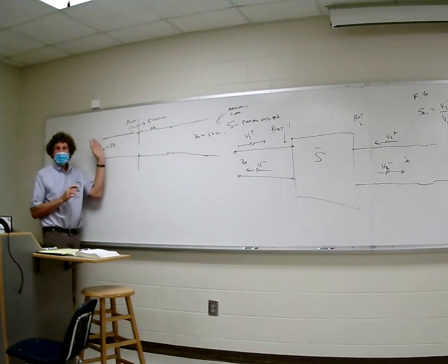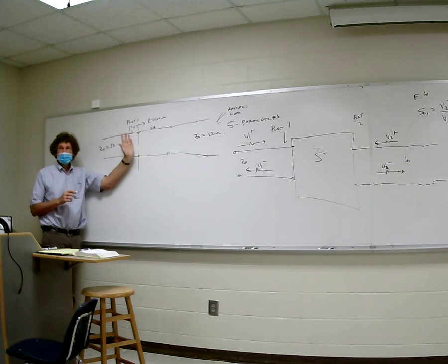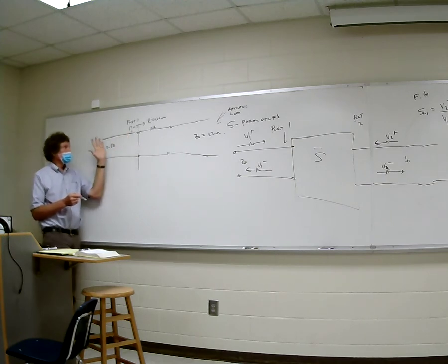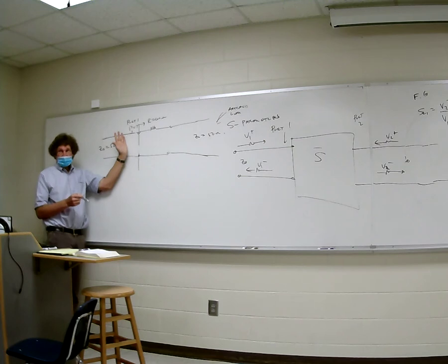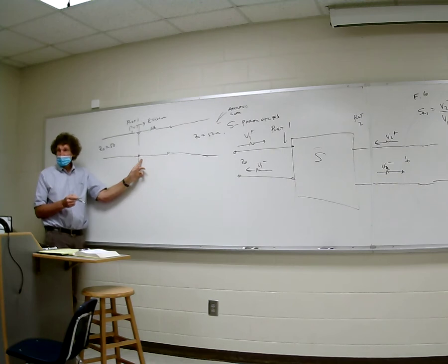Remember, this has got a characteristic impedance of Z0, right? So if I have V1 coming in here, at the instant it hits, it creates a waveform that's going to reflect. It would have the value of gamma times V1, right? And the superposition of that V1 plus gamma V1 plus would be equal to the voltage on the other side, right? It's not equal to V1 plus is what I'm getting.